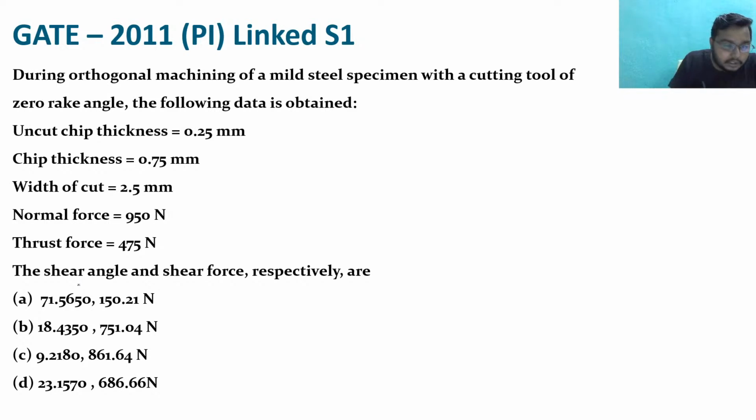In this question, shear angle and shear force have been asked. Remember the formula of shear angle? How can you find the shear angle? The ultimate formula, and the ultimate formula is what? Tan phi is equal to r cos alpha by 1 minus r sin alpha. Right? So give me the answer.